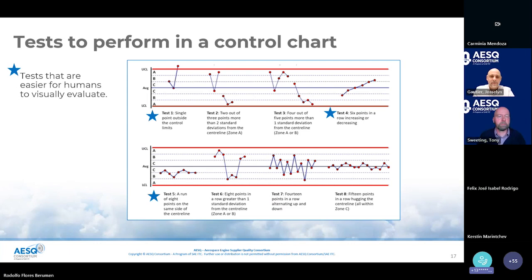Okay. People have probably seen some of this before. It is, funnily enough, the Western Electric rules, but it's generally the way we would try and classify something that we didn't expect to happen. The control limits we draw are there to tell us, I think the process should be somewhere within these control limits. My estimate from 25, 30 points is, I think they should fit within these control limits. These tests are here to tell us something's changed. This is not what I expected to happen. And I'm telling you about it.